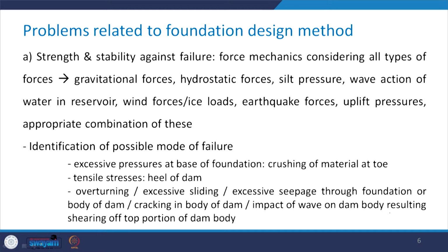Now these can be gravitational forces, hydrostatic forces, silt pressure, wave action of the water in the reservoir, wind forces or ice loads, earthquake forces and uplift pressures. Plus there can be the appropriate combination of these forces which can act on the dam, foundation and abutment system.